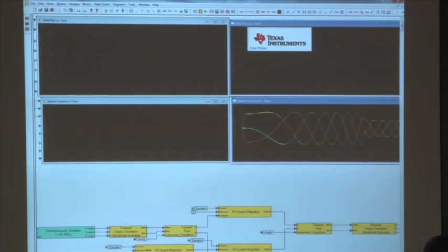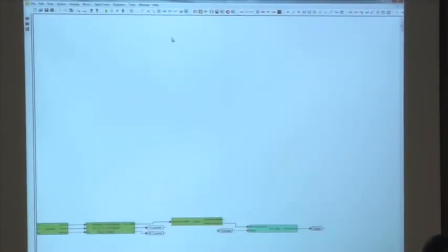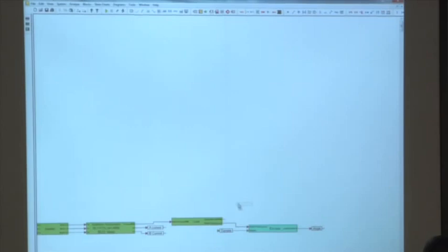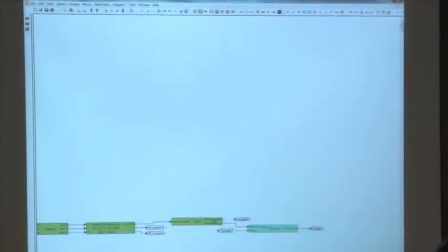One more thing that needs to be done. And that is the output shaft speed in terms of RPM. I'm going to go up to the VAR tool, create another variable, put it on the output of the load block right next to the shaft speed. I'm going to call that variable something creative like speed. And then connect it up to the load block.